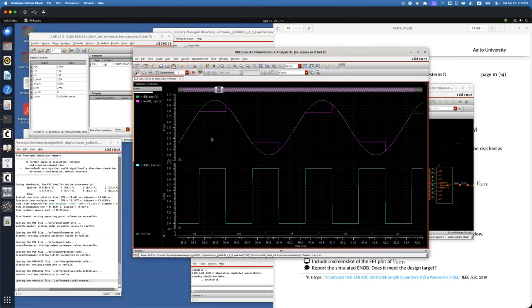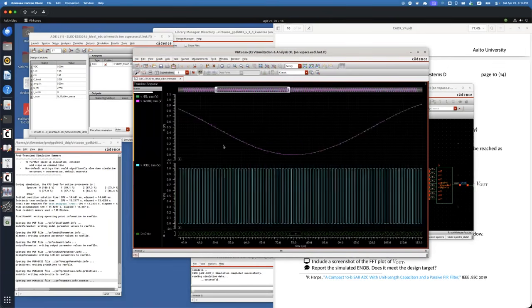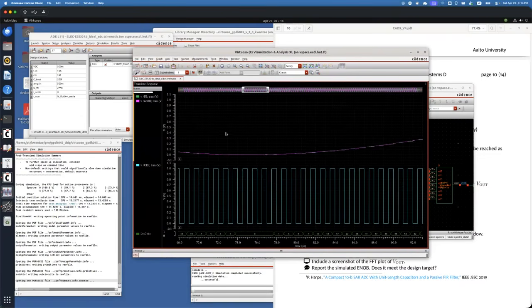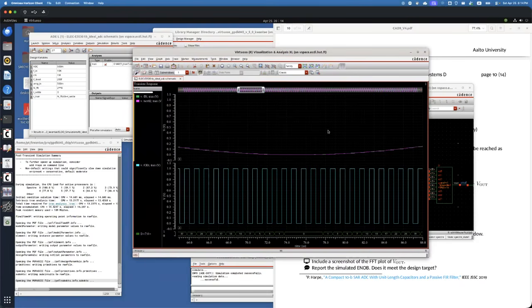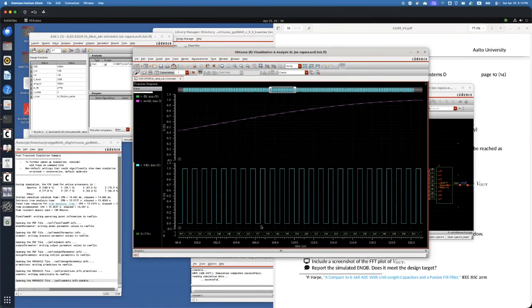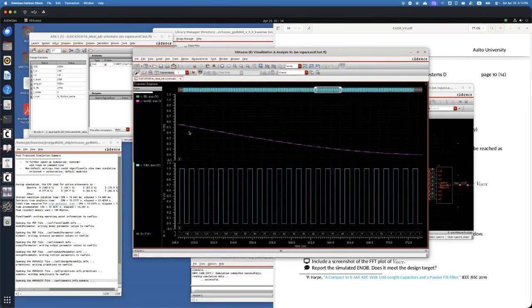Right. Then, if you just press Ctrl R to refresh, you can see it shown as a slowly moving signal. For the input of the ADC, the ideal ADC starts at a low value, so of course it should indicate 0, 1, 3, 5, 7, 10, and so on, going up and up and up, and then touching the maximum value of 255, this way.